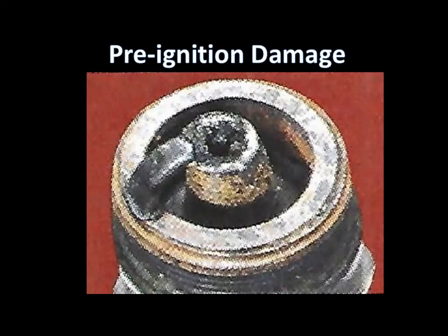Severely damaged spark plug electrodes indicate pre-ignition damage. Inspect the upper and lower ends of the insulator for cracks. Spark plugs with burned electrodes or a cracked insulator must be replaced.